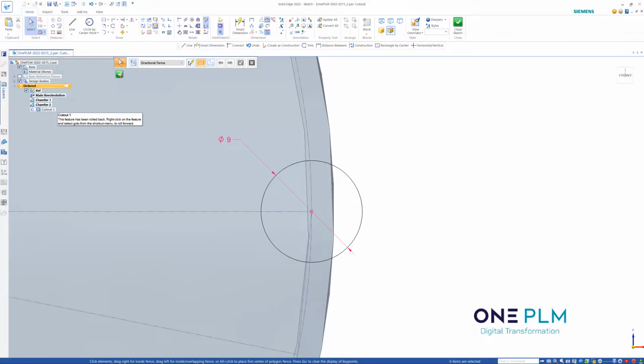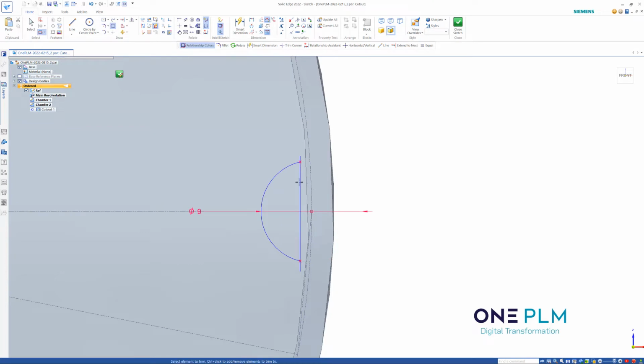So first thing we're going to do is draw a line, because I want to split this into an arc. If you press and hold the shift key, make sure the line is vertical. If you come off the shift key before you finish, it's not going to do vertical. So choose the line command, press the shift key, finish the line, and then go to our trim command. I want to trim that, and then delete the line. We can trim all of them depending on which way you want. Notice the arc is still linked to the end of this line, our construction line.